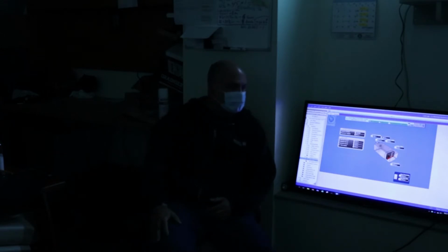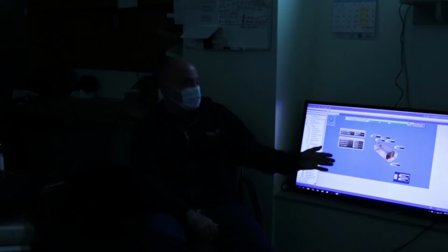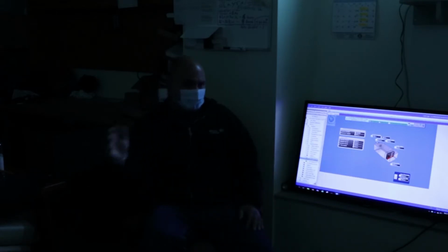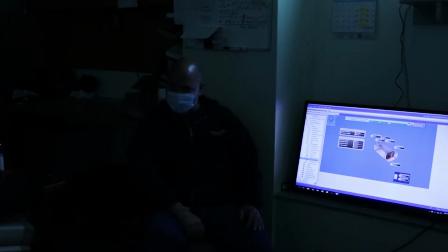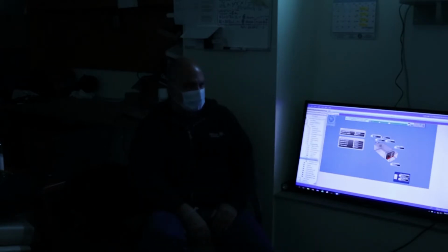If we put the set point on a thermostat at 70 degrees, in the cooling mode it's gonna be 68 to 72, and heating mode is gonna be 68. It won't go to full heating until it hits 68. The PID loop is going to get in the direction, but the dead band is in there. All the VAV thermostats are set up like that.